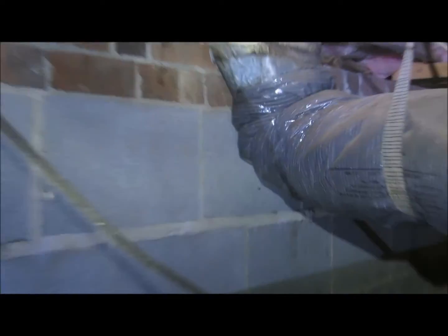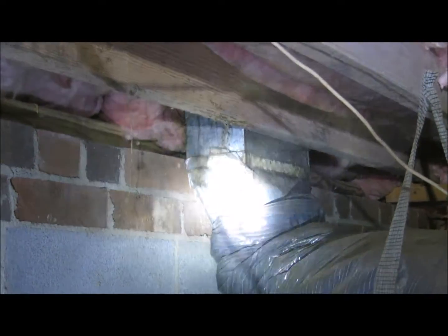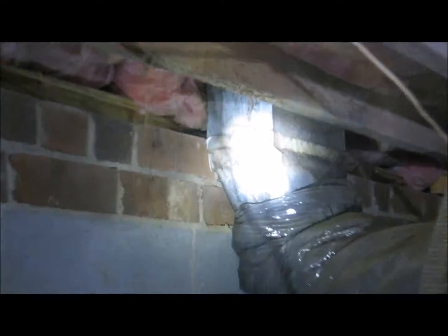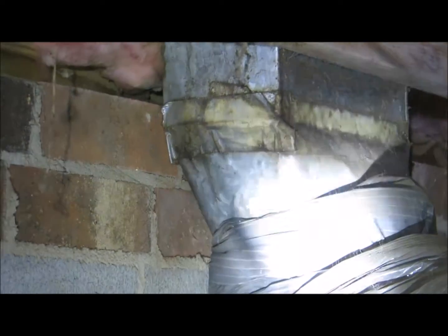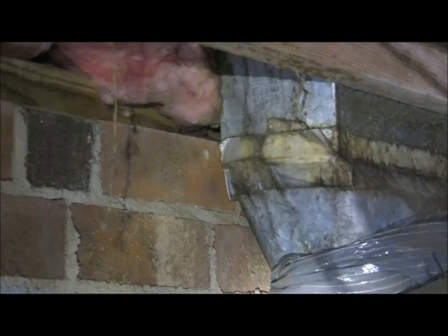Here's another spot where the air ducts are not covering the boot, so these metal boots want to sweat, and again mold wants to grow right next to where it goes into the house. I disconnected this duct from the main trunk pretty much right in the middle, and there is extensive mold growth inside this duct.